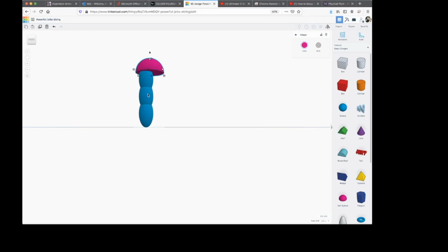is to shift click both of those forms and then come back up here to where your grouping tool was, so the upper right hand corner, and if you go to the fourth icon, that's your alignment tool. So the shortcut for that is L. So I'm going to click the alignment tool and it turns on these handles, right? And so by clicking on these handles, I tell it how I want these forms to align, right?